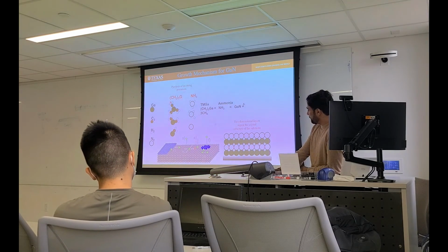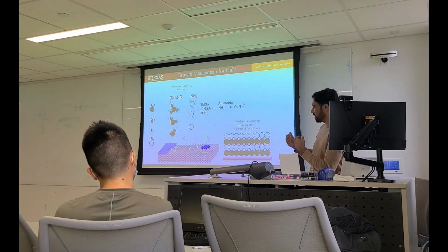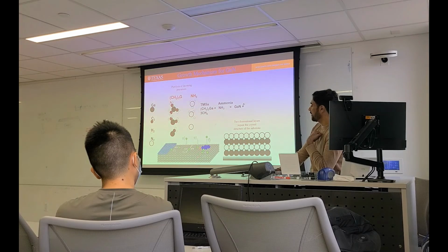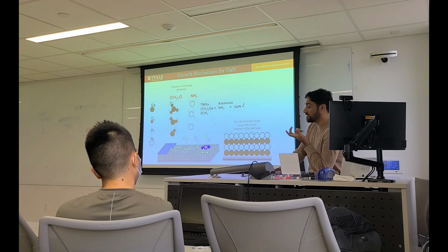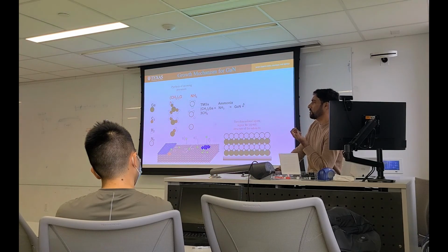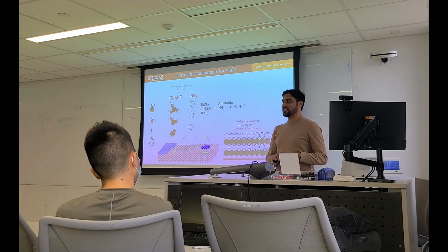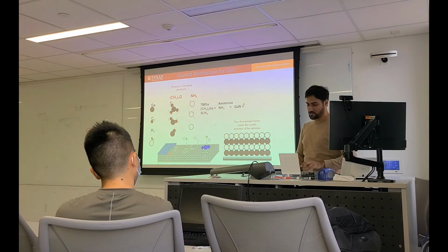So what happens actually, you have a substrate, you grow the epitaxial layer, so your radicals, this one and this one, are moving to the substrate. During diffusion, they react and make the ionic crystals there, the epilayer growth. It is on you how you tune your growth parameters to make a uniform epilayer. But to deal with the strain, you need to introduce buffer layers, or you need to decide your best substrate which has the best lattice parameter, lattice mismatch.